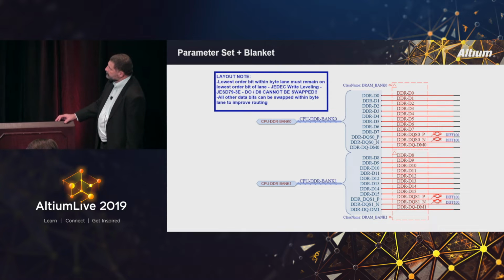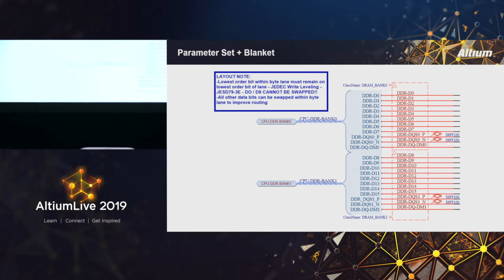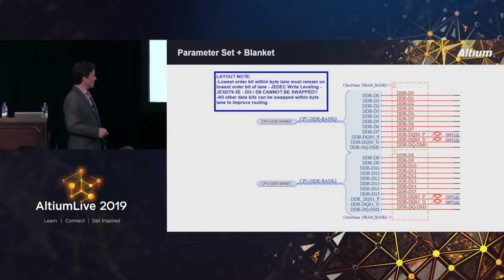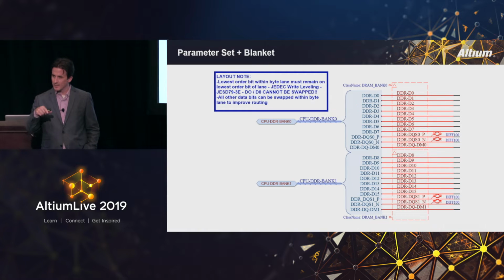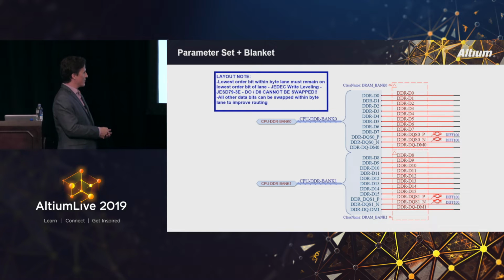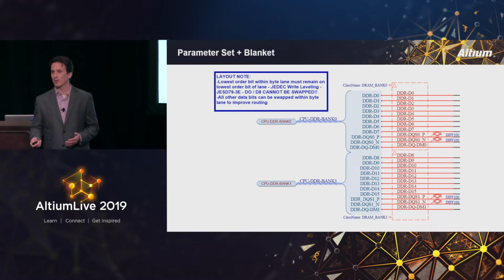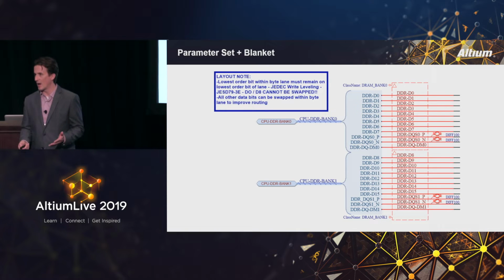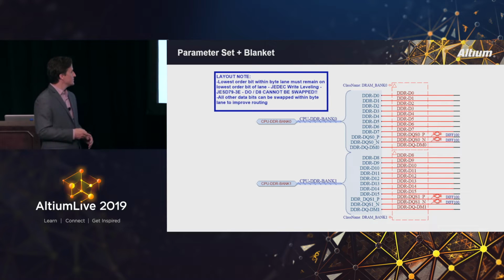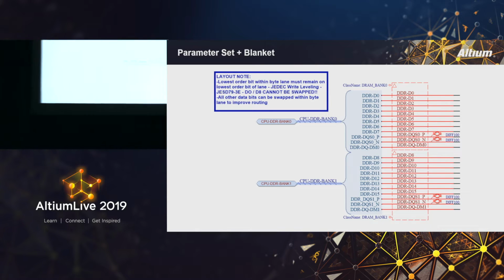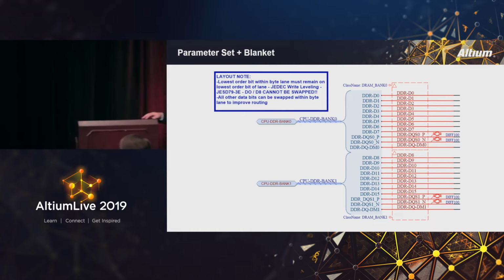One thing I'll say that has caused me problems in the past is the hot point for the net name, which I think is a little dot at the lower left-hand corner of the net name. I've had problems when this is right on this line. That last net does not get included into the net class. So you've got to bring this down one more space. Yeah, it's good practice to have adequate space between your entities on your schematic.